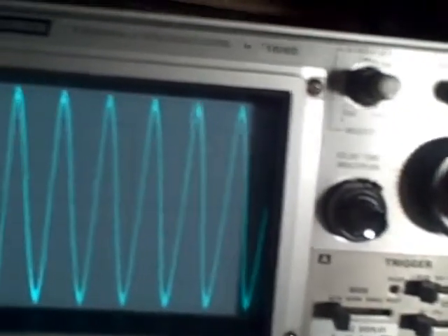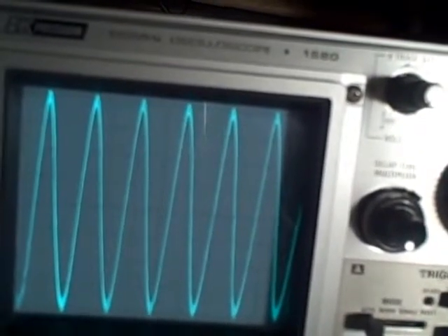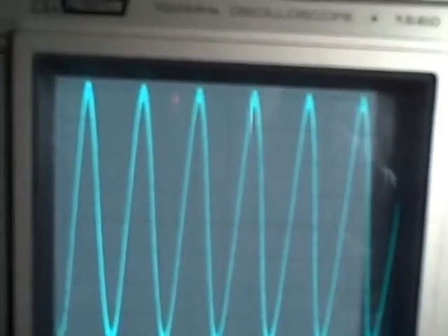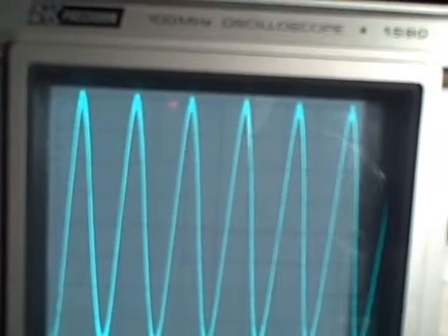But in order to do that, I had to reduce myself to 10 millivolts per division, so I went down a level here, and I had to do the same on my B&K so I can match it. And we've now adjusted the peak-to-peak height so that we are up 4 and down 4 and just touching the graticule on our reference scope.